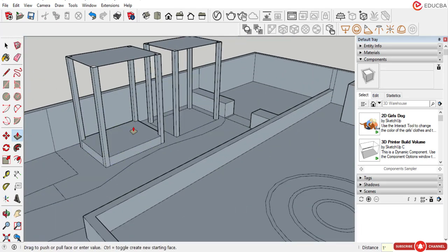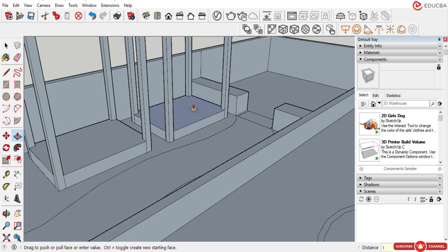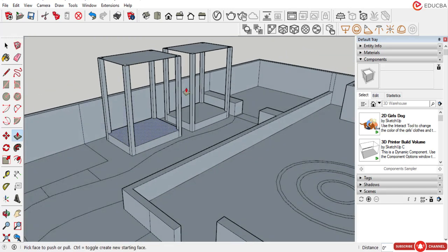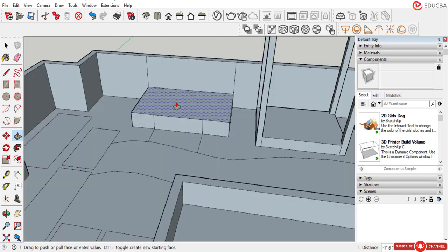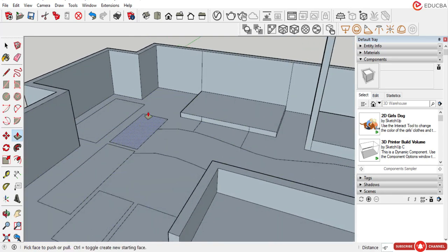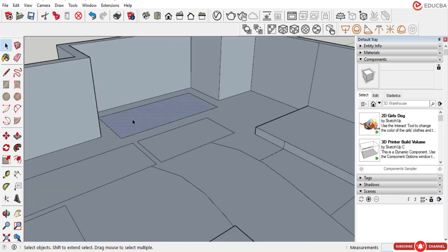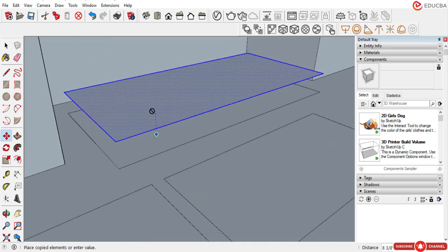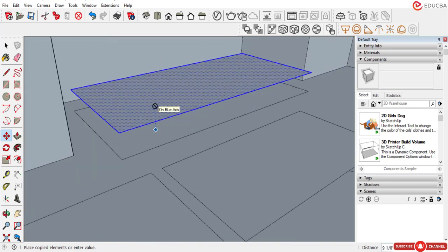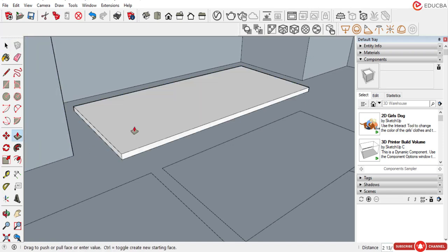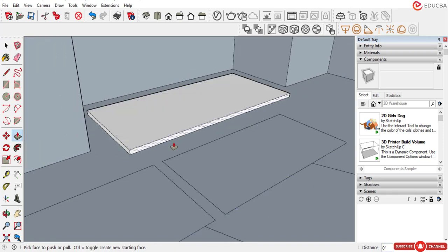Now this is 1 feet, from here 1 feet. Here I will provide the sitting arrangement. Here just provide 6 inch from here, and copy this. So we can provide the tiles here. Just copy only 2 inch, and again push and pull command 2 inch.